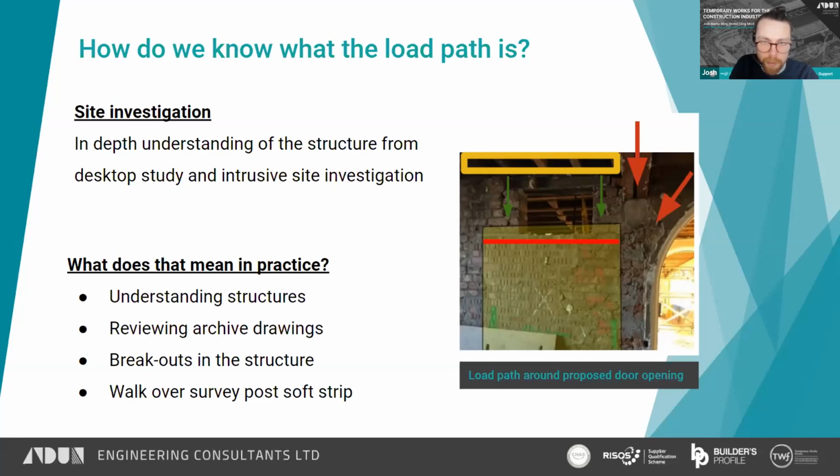It means reviewing archive drawings, that's if they're available, that is. Remembering that just because they're archive drawings, it does not mean that they are as-built drawings. Intrusive site investigations such as breakouts in the structure to expose the key structural elements, confirming assumptions or finding out new information if you don't have drawings of the structure.